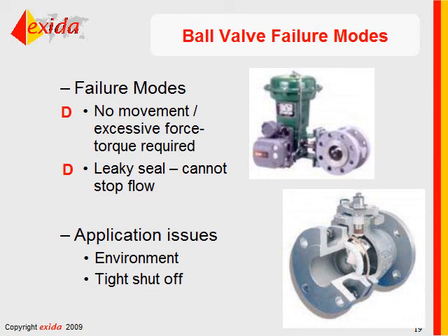So if we do a detailed analysis on a product, on an equipment item, a transmitter, a valve, actuator, etc., we know what the dangerous undetected failures are of that product. And keeping in mind that the objective of our proof test is to detect failures that are undetected by automatic diagnostics, we would be able to specify pretty detailed proof test procedures.